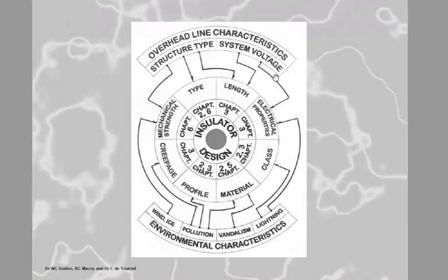And the system voltage is going to tell you the electrical properties which you expect from this insulator, either from a lightning impulse perspective, a switching impulse perspective, or an AC wet and dry flashover perspective. It's going to give you the rules for the electrical properties which you need for this high voltage insulator. So you see, system voltage already tells you length. You're going to need a dry arcing distance, a connecting length, an insulation length, a creepage distance.